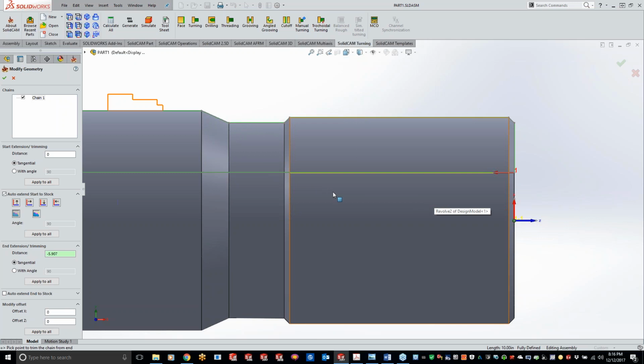So if, oh, go ahead. Just wanted to bring up that Ben made a nice comment there. Usually, if the outer thread diameter is smaller than normal, after the thread I make a second finish pass at the same diameter to deburr the threads. Yes.